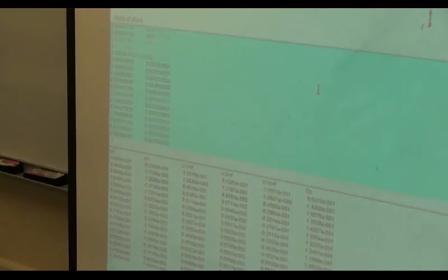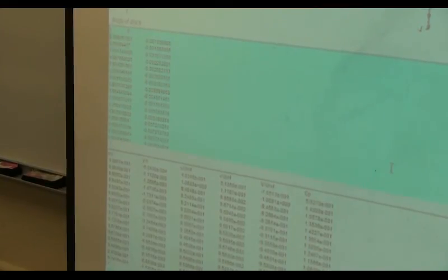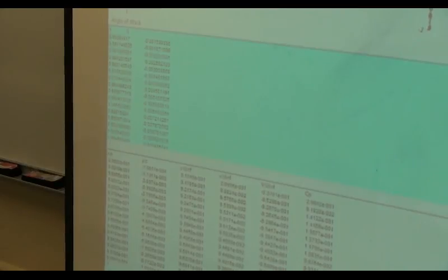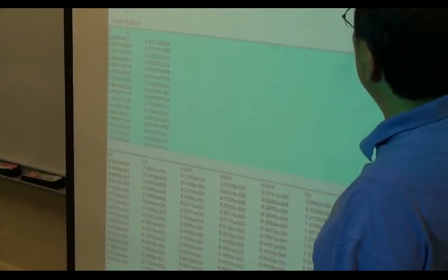And I'm going to go all the way up. I'm going to remove those two also. Compute. Yeah, okay. Still a few more. I probably don't need this one either. Compute. Alright. So pay special attention very close to the trailing edge. If you have way too many small tiny panels clustered up here, it is going to create jumpy data points, which is error.